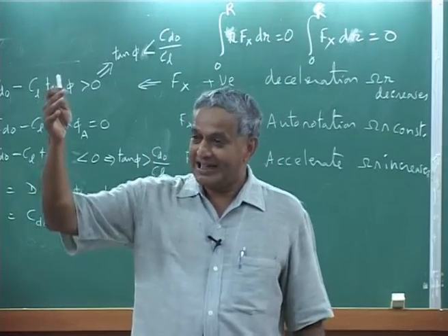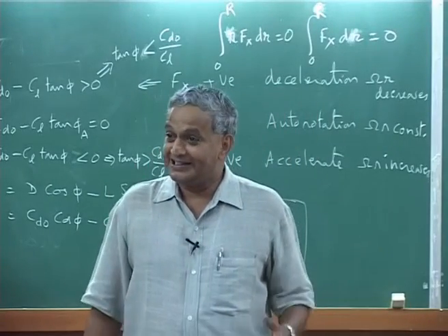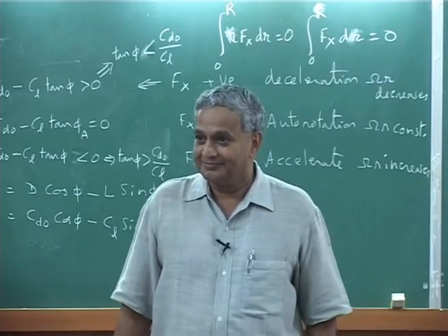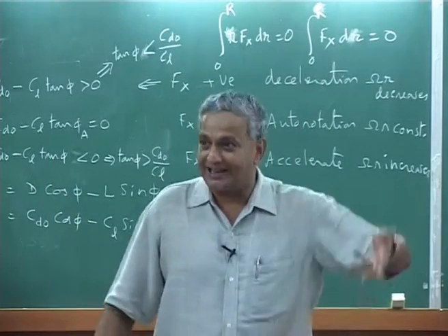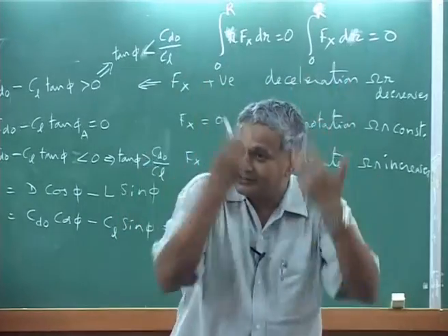Sometimes if your angle is already large, you increase the collective, you may be going down further. Then it defies your logic, I have to reduce the collective so that I get attached flow, after that climb. But usually the instinct says, if I reduce the collective, I am going to go further down.